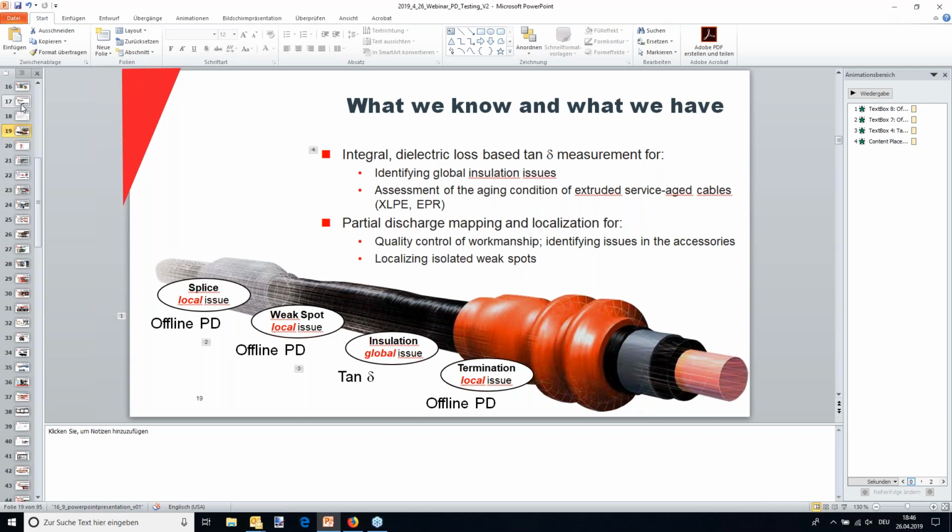Also for VLF testing, I would not do this when you have other equipment connected if it's not necessary. There are some systems in the US, these network systems, and some of these network operators cannot isolate the transformers.